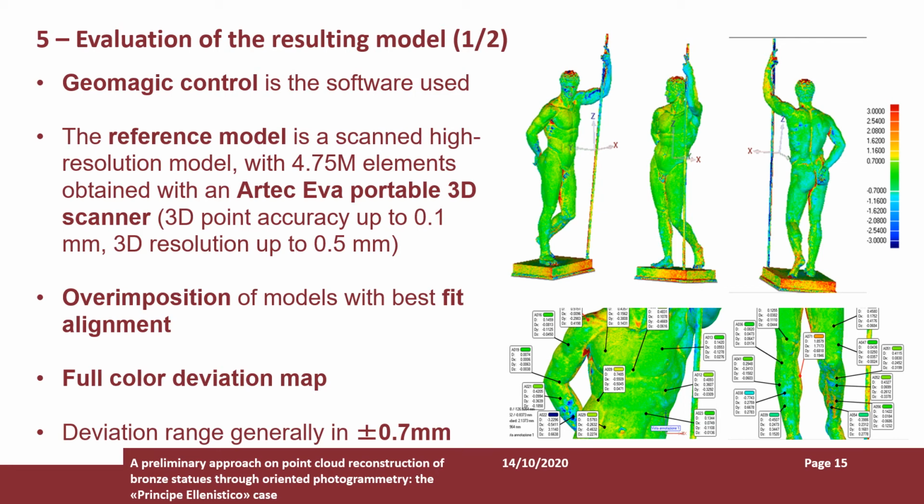other similar software. The reference model we used was a high-resolution model of about 5 million elements, obtained with an Artec Eva portable 3D scanner, whose 3D point accuracy is up to 0.1 mm, and the 3D resolution arrives to 0.5 millimeters. The overimposition of the obtained model to the reference one has been done using a best fit alignment.